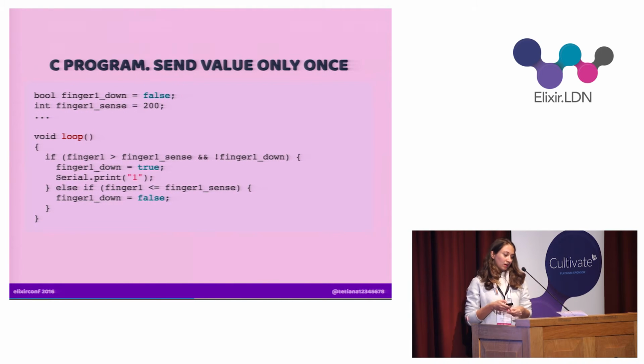Okay. The problem with that program is that if you keep holding the pressure, it will keep sending the values. But if you want to register the event just once, you need some condition checking that whenever someone presses the key, it registers once, and then registers again when they take it off and press it again. So you don't have the events coming constantly. You don't need that.